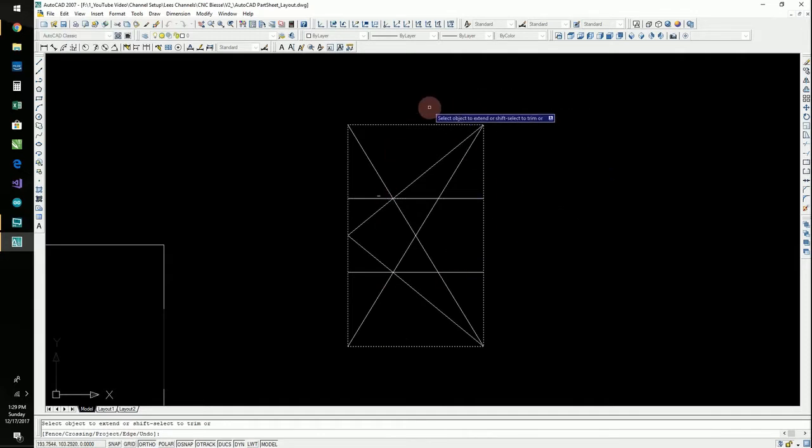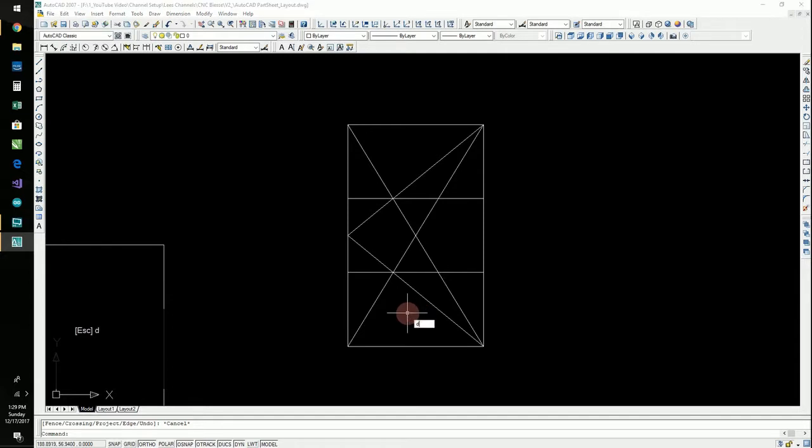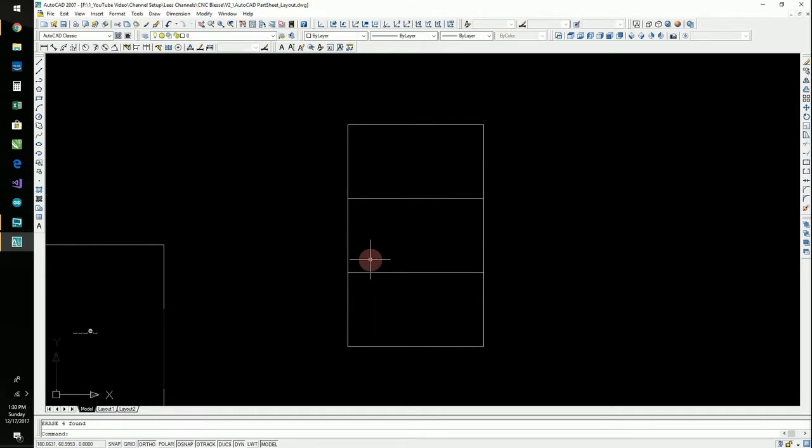So we could do it the same way the other way, but for right now, to prove to you that this is what it is, I'll hit DI for distance, and I'm going to click there to here, 16.666, here to here, 16.666. That's weird. Okay, I'm going to take this and hit E for erase.